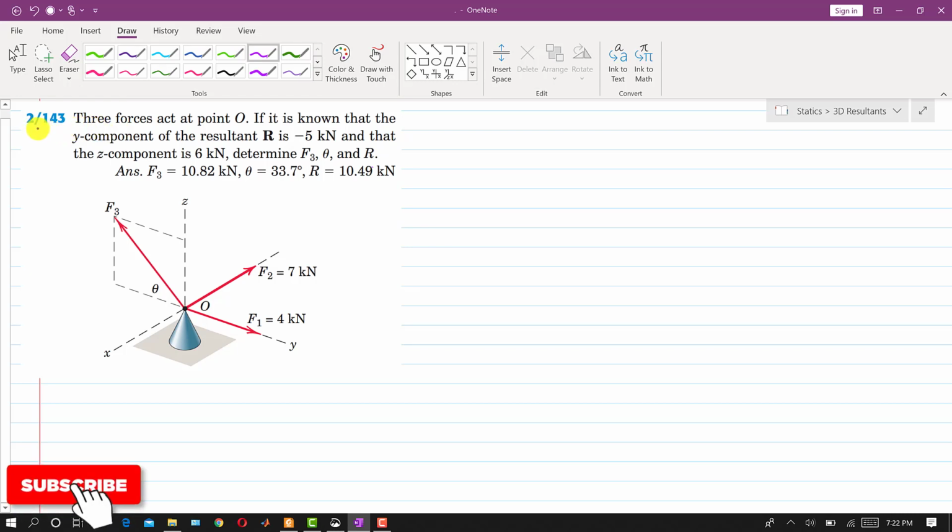I'm going to solve this problem 2143. In this problem it is said there are three forces acting at point O. So these are three forces which act at this point O, and it says that it is known that the y component of the resultant is minus 5 kilonewton. So Ry is equal to the summation of all forces along y, and this is equal to minus 5 kilonewton, right?